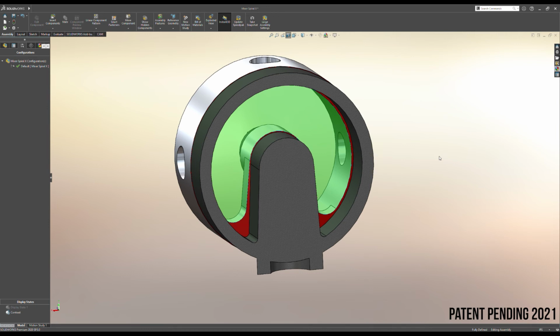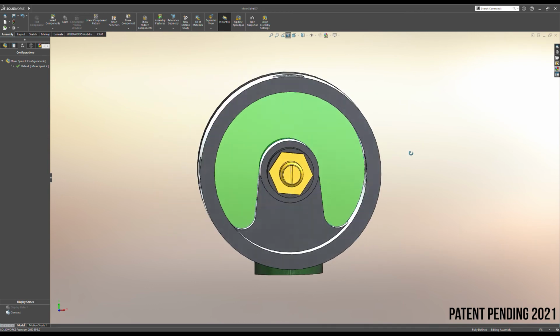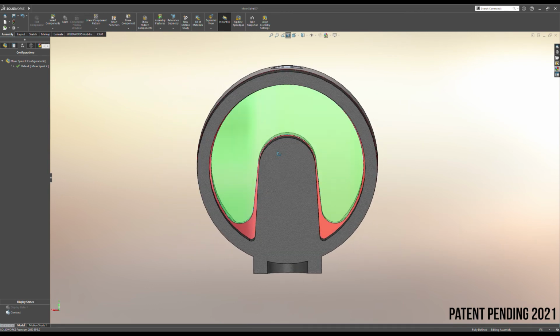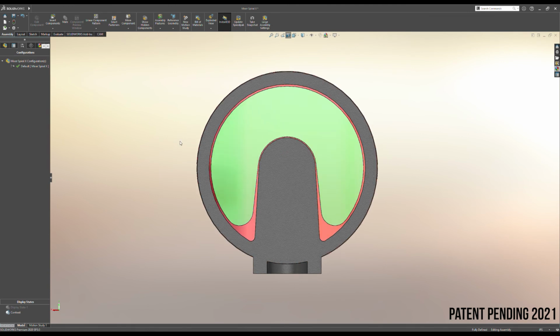And you have an abundant supply of air, which allows you to run on the lean side of air-fuel ratios, which is good for emissions, including the hydrocarbon emissions and the NOx emissions. Because we can take the flame temperature down by running in a fuel-lean scenario, we can reduce the NOx emissions. So this is just a great overall solution in terms of emissions and air-fuel ratios.